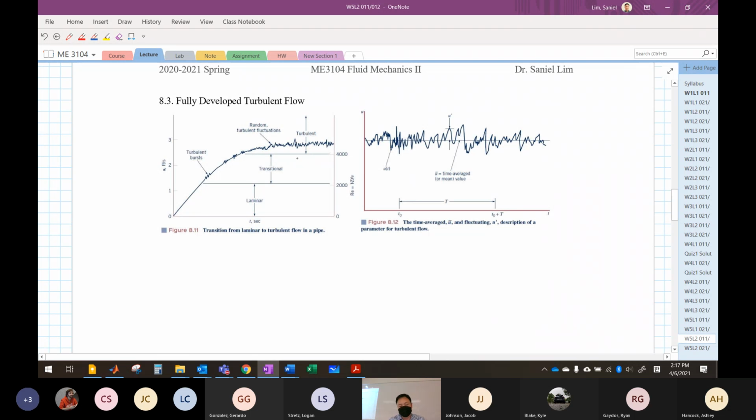For example, let's increase the velocity very slowly, so it's not going to make small eddy currents mix and so on. Let's say it's just the pure effect of the velocity increase. From the slow velocity, it's laminar flow, and the velocity increases linearly. Then after a certain point, with the Reynolds number around 2000, you'll see a little bit of eddies there.